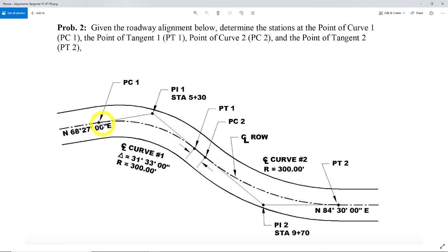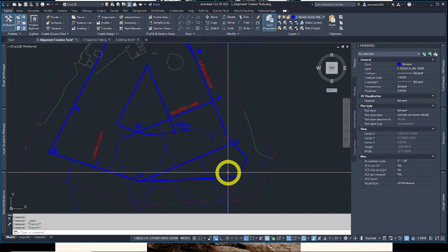When something is free, a line, curve, or spiral, it's dependent on another alignment on both ends. So it's basically free to move on this end and this end. And then floating, it's free to move on one end. And then fixed, it is fixed here and here essentially. So 3 permutations on how you can free, float, or fix a curve or a tangent section as you move up or down in alignment. Those will come into play a little later. We won't dive into them too deep.